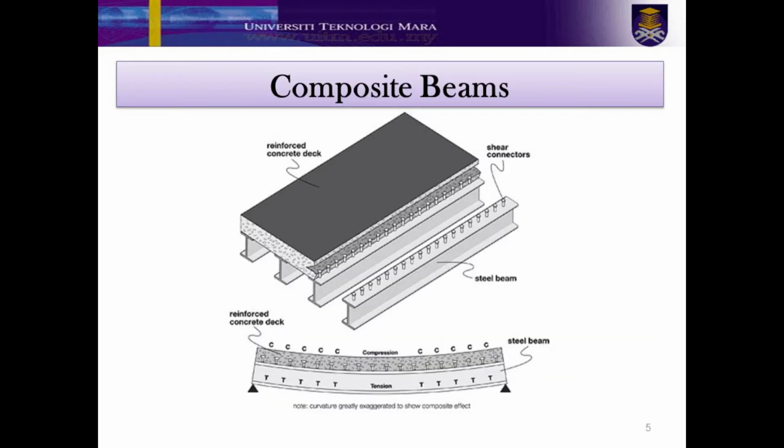Composite beams are universal beams which have a reinforced concrete slab cast, such that shear forces can be transferred between the universal beam and the slab. Composite means that the steel structure is fixed to the concrete structure of the deck, so that the steel and concrete act together, reducing deflections and increasing strength.